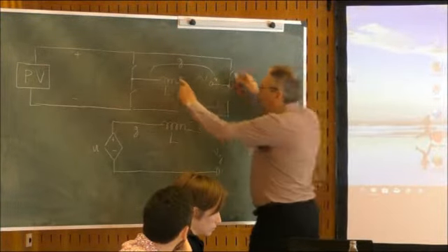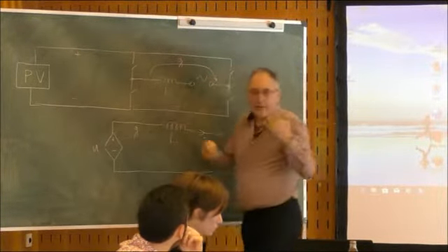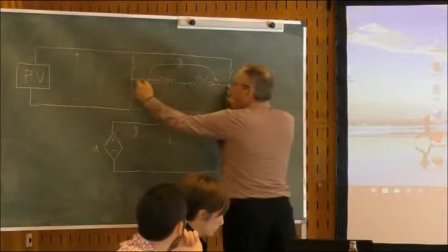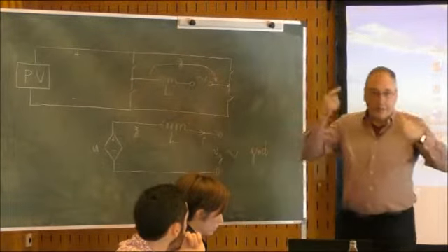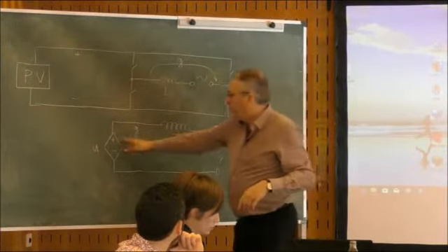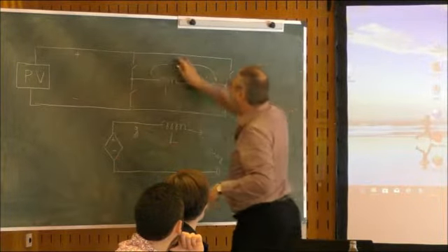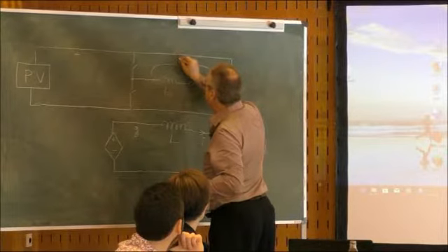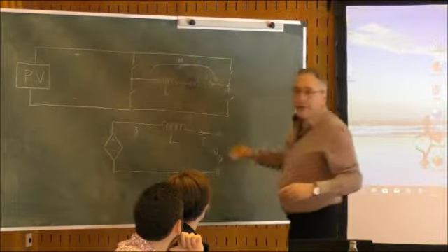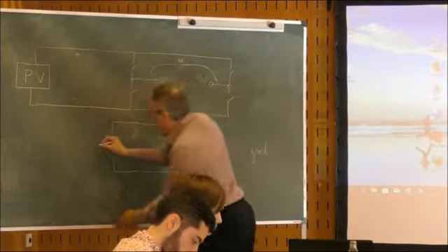So, the switches work very fast, as I said, several tens of kilohertz, and then you average the signal that you obtain between these 2 points. Because it's a very high frequency switching signal, you average it, and this average signal is this G. Oh, why did I write U here? Let's call it U, it fits better with the pictures that we had earlier. So the averaged voltage between these 2 points, we call it U. So I delete G, and this is U.